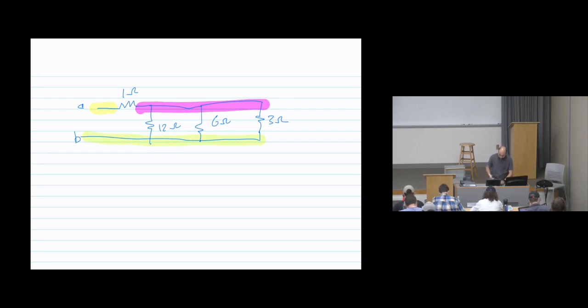Then, if someone says, let's make the observation between the 12 ohms and the 1 ohm. Are those in series or in parallel? Actually, they are not in series, not in parallel. They are not sharing the same node. They are not common in two nodes. So what should I do? Again, whenever you see something that is not in series, not in parallel, then don't do this. Look for other resistors. So we will not do it.